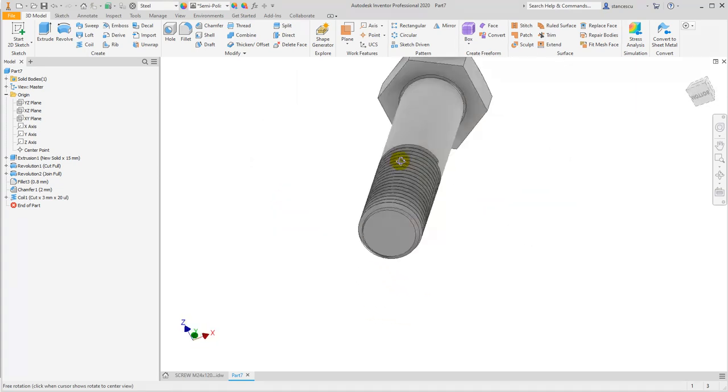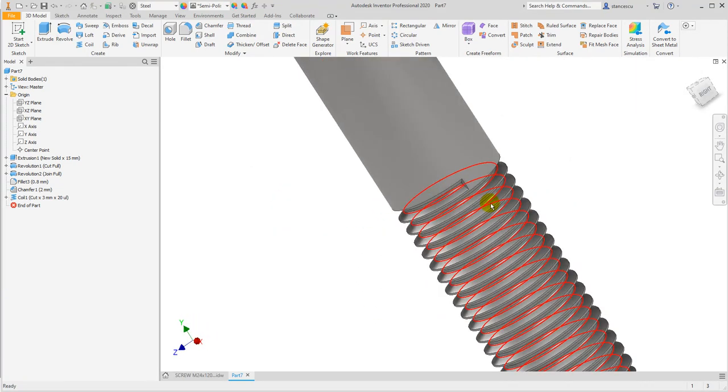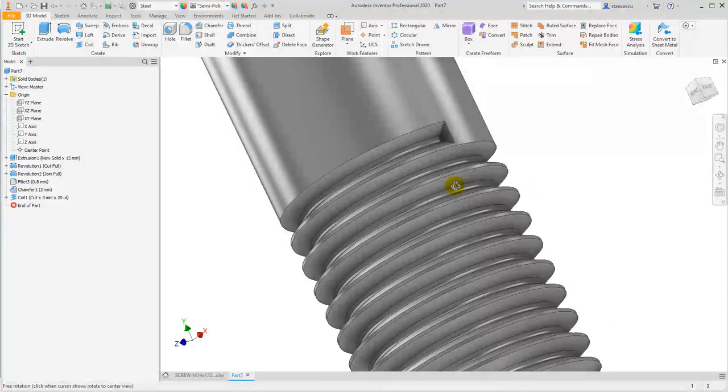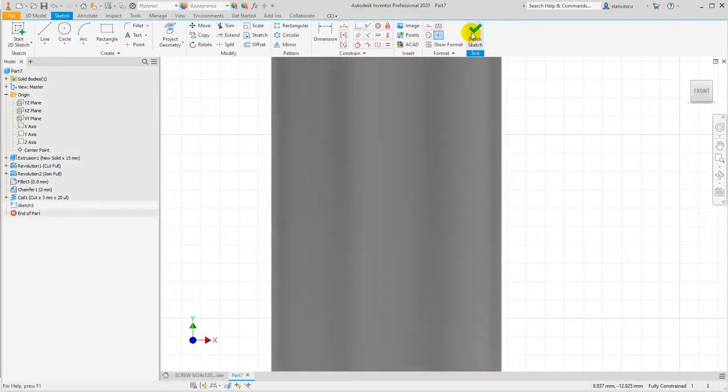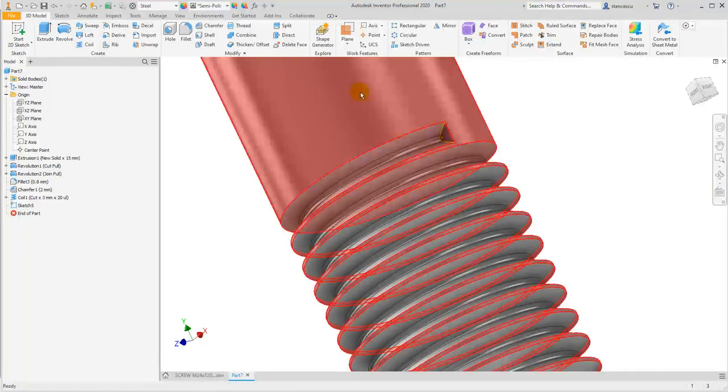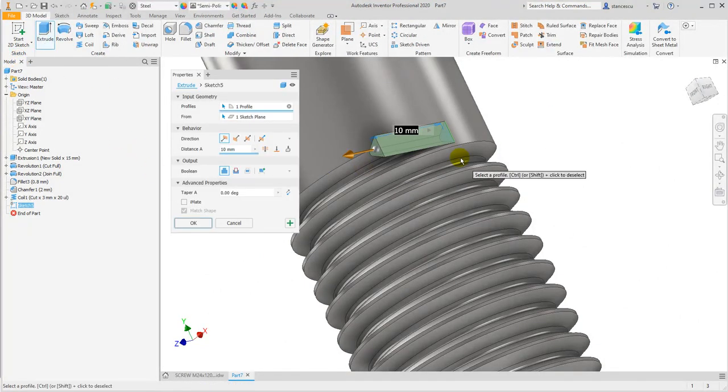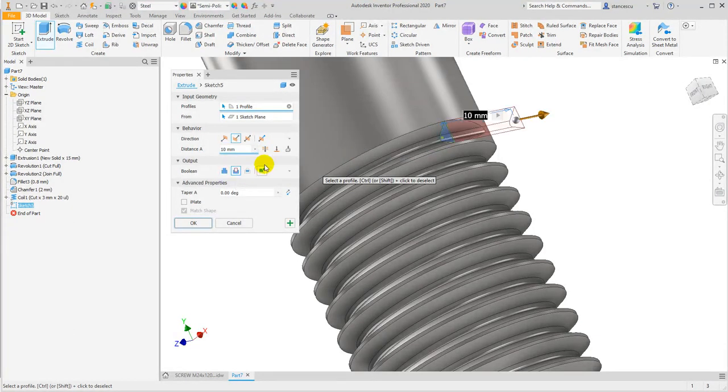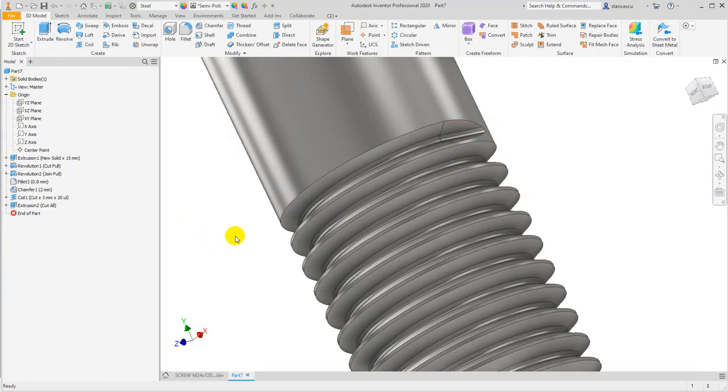See, the coil is really made on this screw. Now we have to finish this, because no tool can do it, only 3D printing, which can do anything. We create a sketch, we finish the sketch. Extrude, not with adding material, but with subtracting material all the way. Okay, F6,